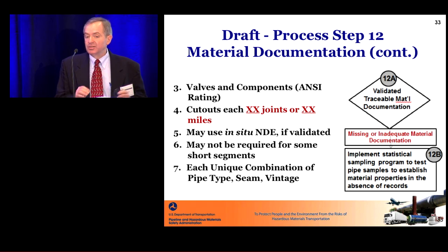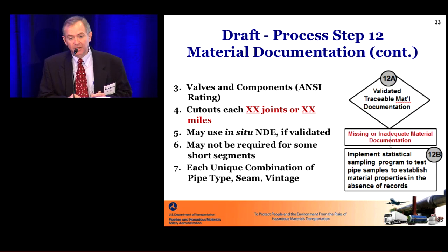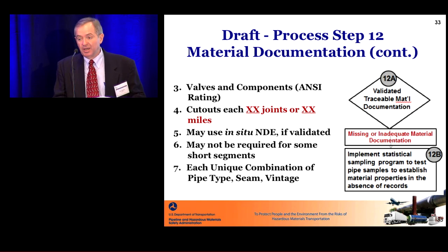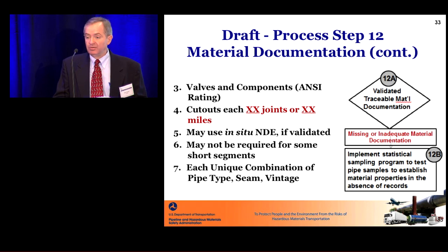Should we be able to use in situ NDE methods? If so, what should be the procedures and the tests that we should use? That's something that PHMSA has worked with several operators on, and we have seen a number of test results. The one thing I've told anyone using an in situ method is to make sure you check it by destructive test methods. In other words, get samples of your pipeline and test them to make sure any in situ method you're using gives you good results.